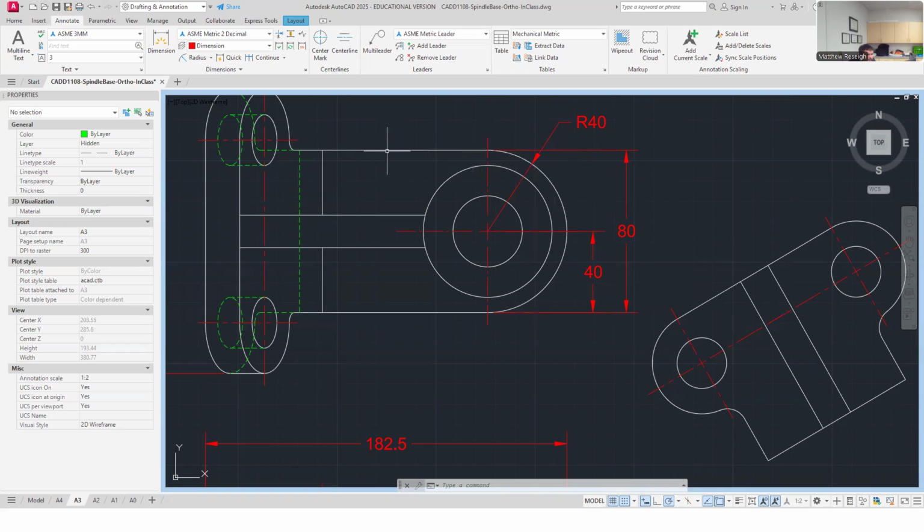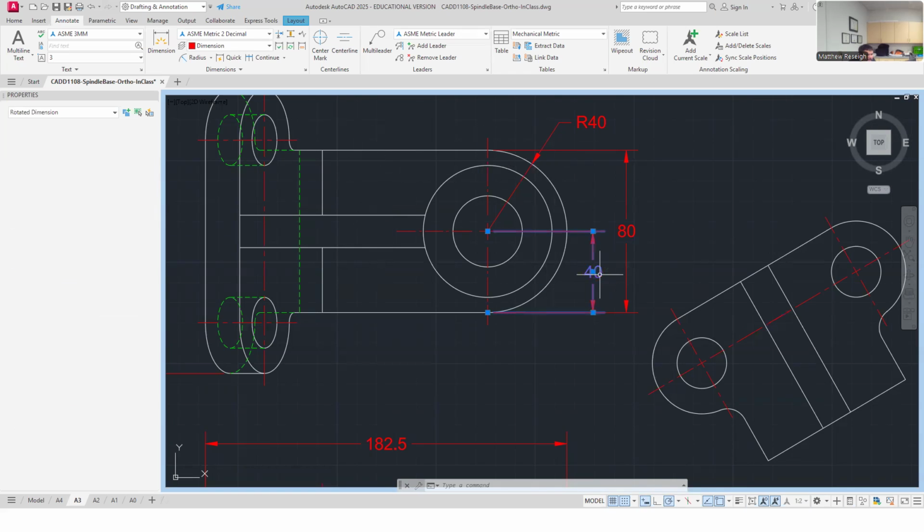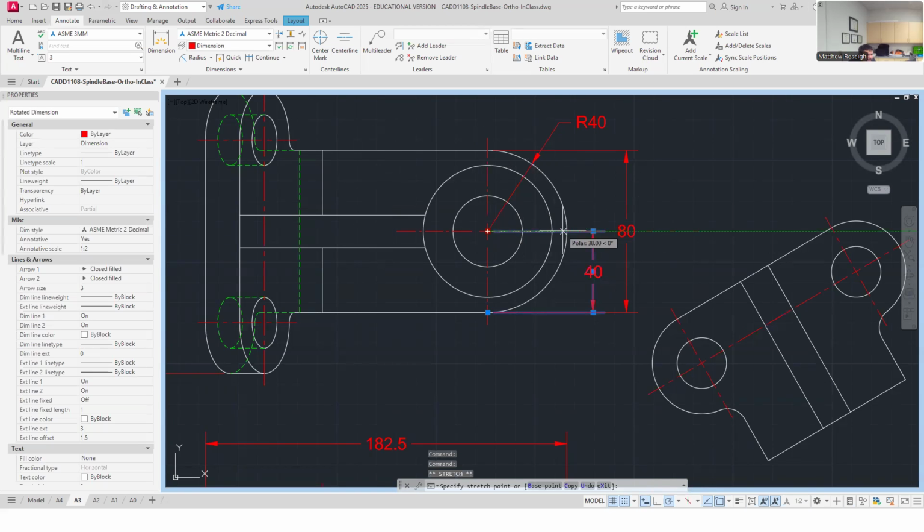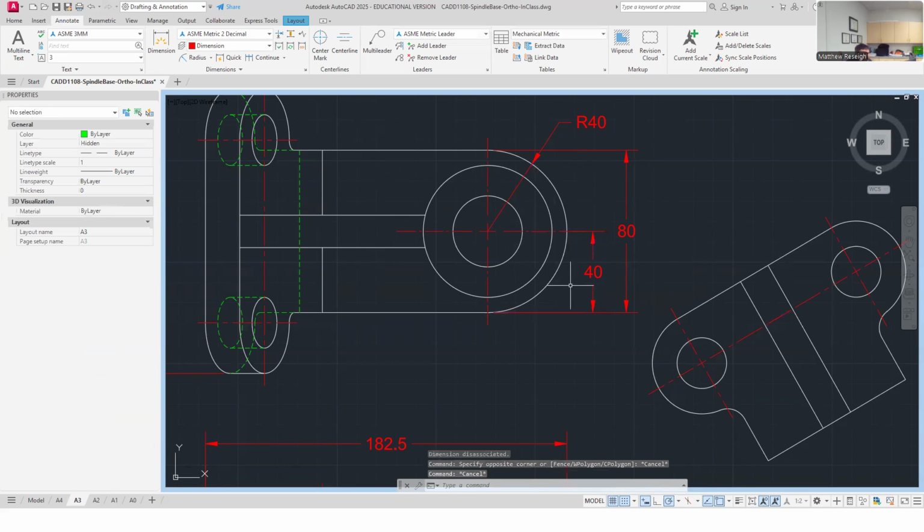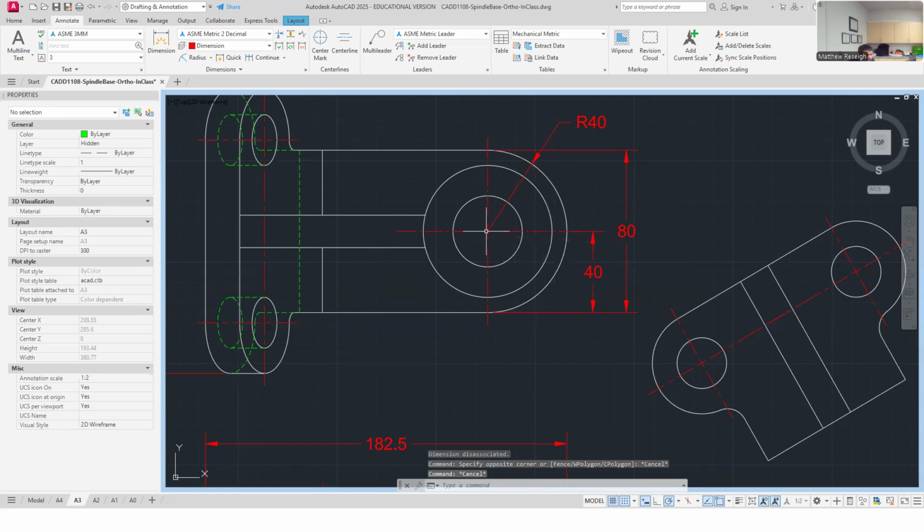It has some flat depth to it across here. And then I'm establishing where that flat depth is in relation to this control. So I think of this as my maze: from this center point, I go over 40, and then from there I come back this way. I'm always working off of the center here. So I follow this as a little maze, and this is where I think a lot of people get confused and dimensions get missed, but maybe because I put that size on there, someone is able to figure it out.